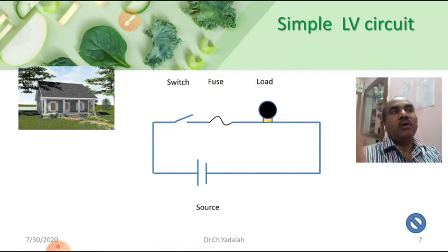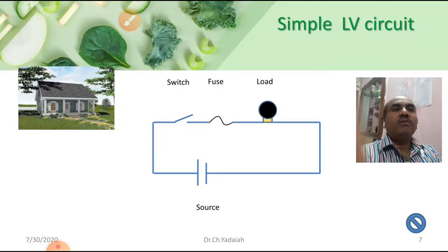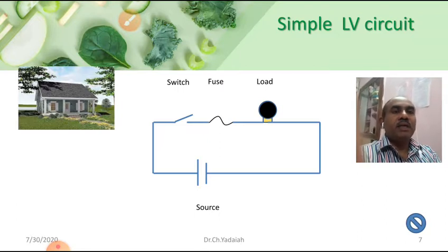So an electrical arc is very dangerous compared to normal fire, which is a wood fire, a diesel fire and a kerosene fire. But those can be quenched by using different media. If possible, we can use water also to quench the fires. But whereas in our electrical fires, arcs and flames cannot be nullified by using water. We require special purpose materials.